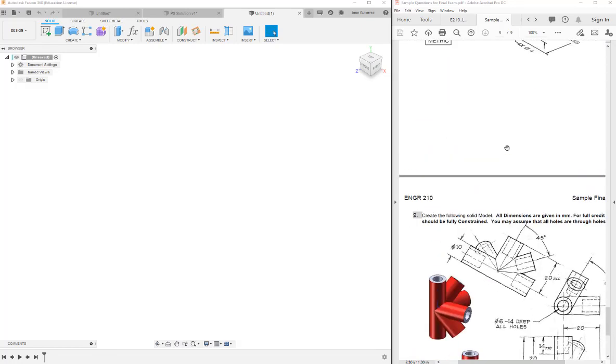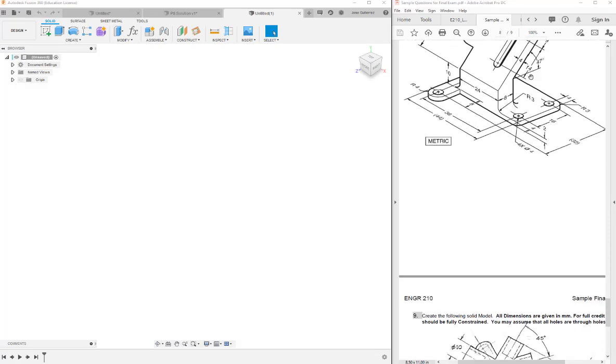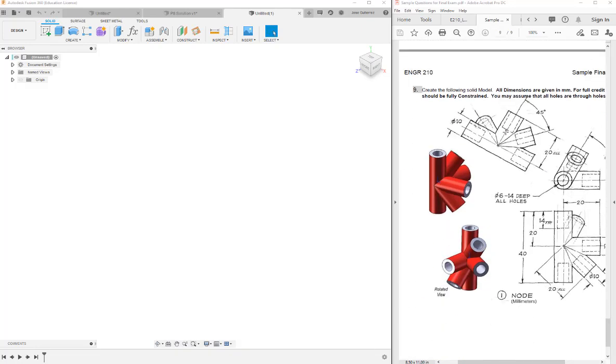going to be different. Where up here we were using extrudes primarily. What we could be using here, there's actually several tools. You could be using lofts or sweeps. Sweep would be preferable to loft because the cross sections are constant. But what I'm going to be using is revolves, because I think if you are to use revolves, that should minimize the number of sketches we need. And so what I'm going to try to do is get this done in 2 sketches.